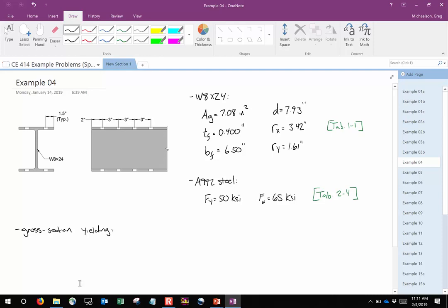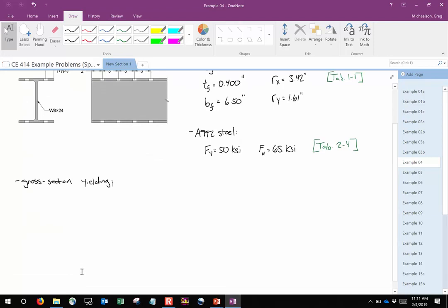For those of you that are in concrete design, today we just looked at Mn, the nominal moment capacity. So Pn would be our nominal axial capacity adjusted by phi to get a design value. So ultimately what we're computing is a phi Pn. Because there's two different limit states. For each, that's a good question. For each limit state, there is a design capacity. It's all about which one controls. That's a great question.